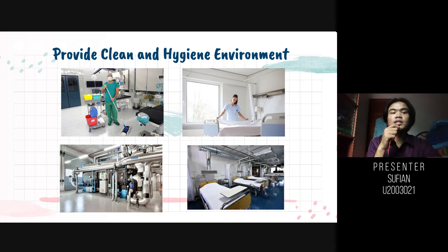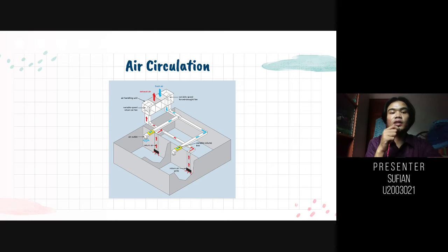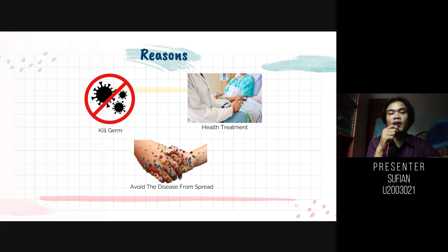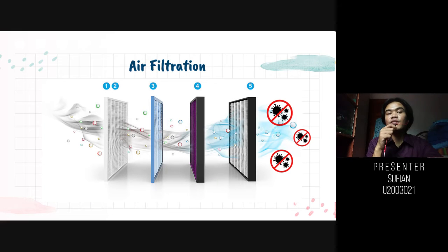There are a few reasons why a medical facility needs air conditioning, because proper air conditioning will help the medical facility, such as a hospital, to prevent disease and help the treatment of certain diseases. The reasons for air conditioning in a medical facility include the need to limit air movement in different departments and between them, and specific requirements for airborne mechanisms, viruses or dangerous chemicals and radioactive substances to be diluted and removed in respect of ventilation and filtration.